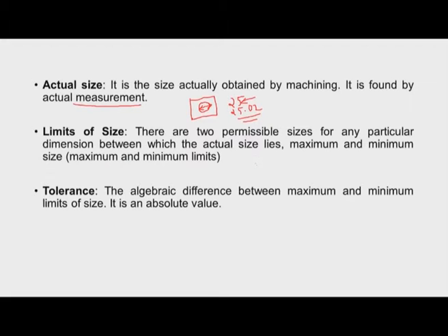So, if we take the example of the shaft, the basic size say it is 25 mm as suggested by the design engineer, and he also gives some tolerance, it may be 25.01 mm, or it can go below 25 to 24.99 mm.